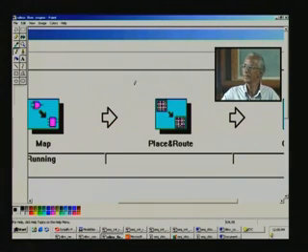I have personally experienced, for over 3 million gate designs such as video scaling, it has taken over 72 hours in both synthesis as well as place and route. It is just to give a rough idea of how time consuming the process is, and the more circuitry, the more time it will take. For this particular design, it has hardly taken a minute or two, and this is a very small design.